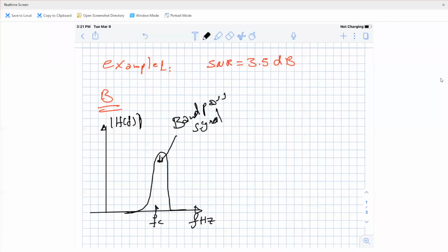Now we have another technique. We are going to transmit the same information, but with the following modification. This time, this will happen. Look. Now the signal level is reduced while the bandwidth is increased. For what? To keep the same amount of energy. So we have the same amount of energy in time and in frequency. And if you follow this method, for example increasing the bandwidth, it really enhances the communication system.